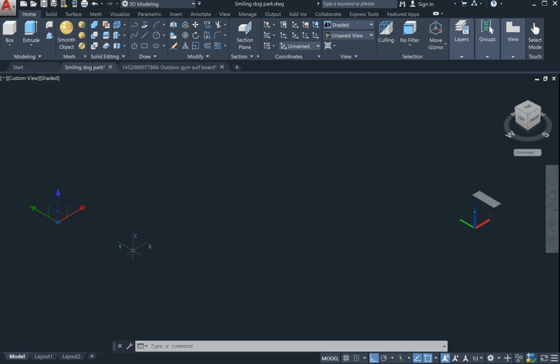It could be in his drawing, this building, and he had this part there, and then he got it off of that file and saved it. So that's where it's locating it. Don't freak out. Like I said, zoom, enter, A, enter.